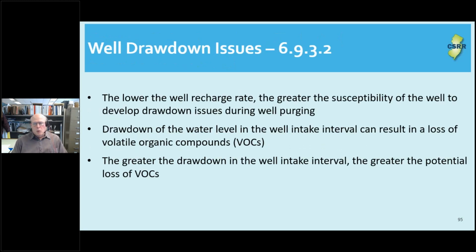One of the main goals in a remedial investigation is the vertical and horizontal delineation of the contaminated groundwater. In the pursuit of that goal, monitor well depths target zones of groundwater contamination, not zones of elevated well yield. That action results in a large percentage of monitor wells being installed in shallow, fine-grained, low permeability material. These wells frequently have low recharge rates, making them very susceptible to water level drawdown during well purging.